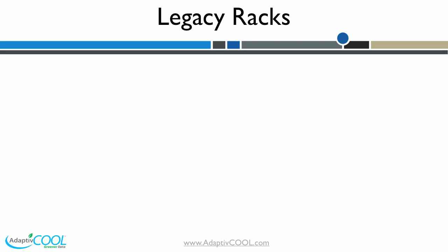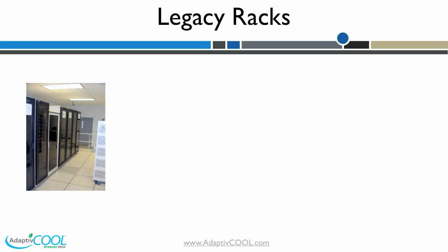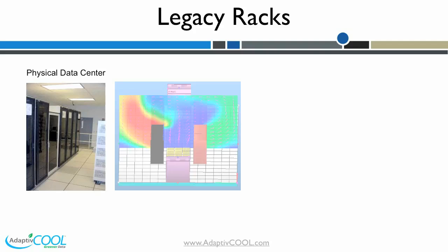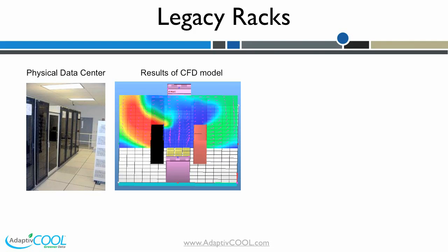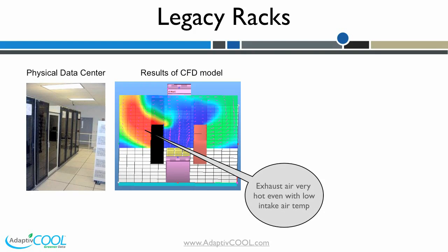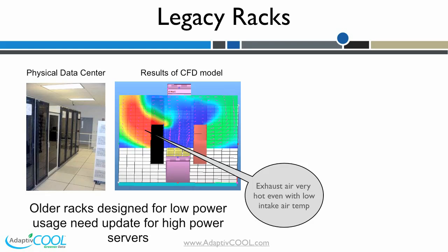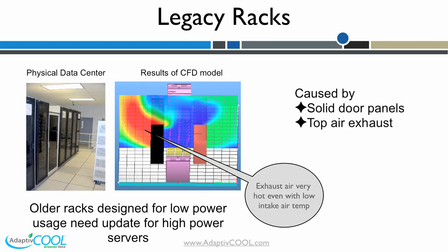Some data centers still use server racks with plexiglass front doors. This severely restricts airflow into the rack and limits cooling. For today's high-power servers, these legacy racks can cause overheating. These doors should be replaced with perforated panel doors to enable higher airflow.